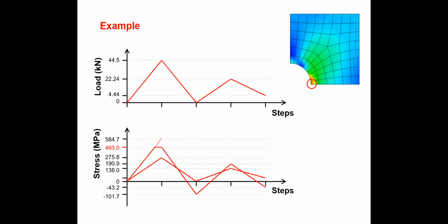So stress is not accumulating too much. So this is kind of warm up. Okay. So you can use this kind of technique when you use some machine element. You can preload it and remove that load, and you can apply the required loading pattern. So did you understand what I'm explaining here?